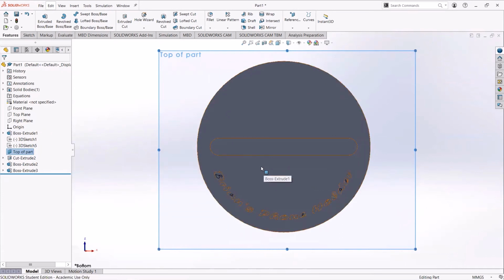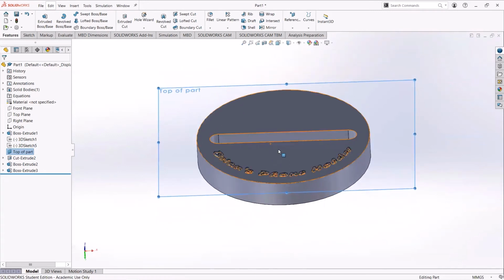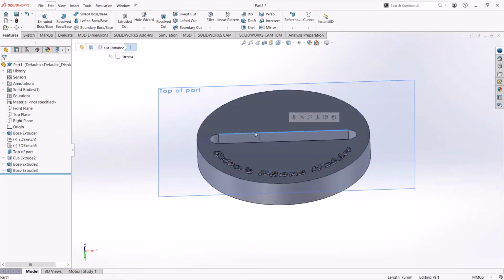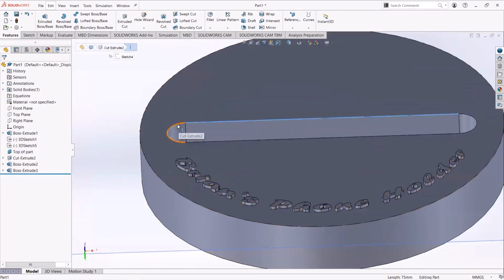Okay, cool. So to make our part look less bulky and maybe look a little bit sleeker, what we can do is we can trim the edges of our part. So specifically when we put our phone inside, we want it to easily go inside. So what we can do to do that is select these edges. And the way we're going to select these edges is by control and clicking on all of the edges that we're going to clean up.